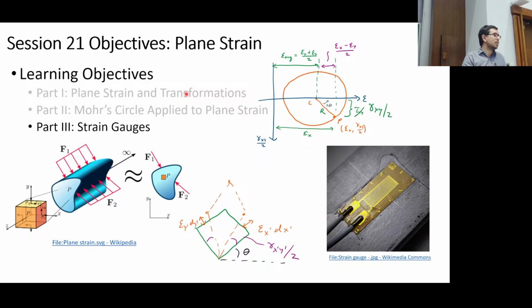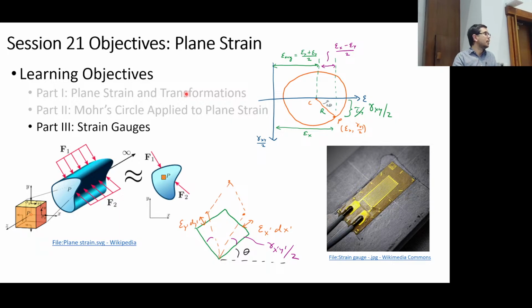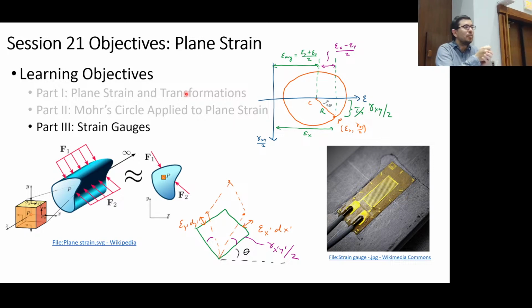We need to understand what's happening on the surfaces. That's why people care about cracks so much. Again, something you should just get out of your mechanics class. That's why people take those. If you ever watch some of these documentaries about plane wings that have failed, you might see a person with a little, not microscope, what are they called? Magnifying glass going along the wing looking for any cracks. Because if you have a crack, it can start to propagate, meaning grow.